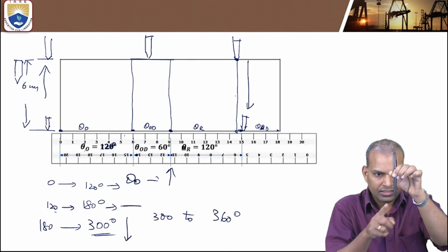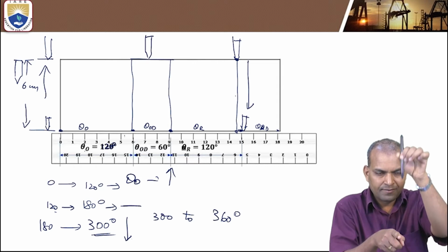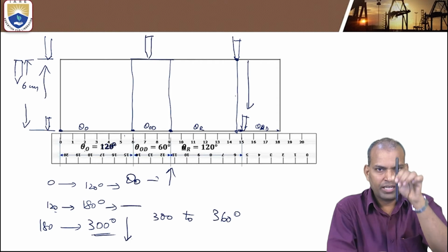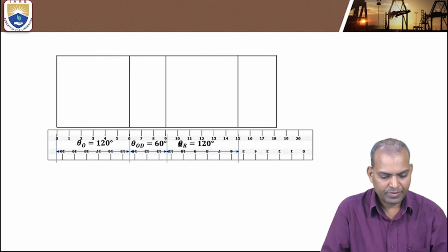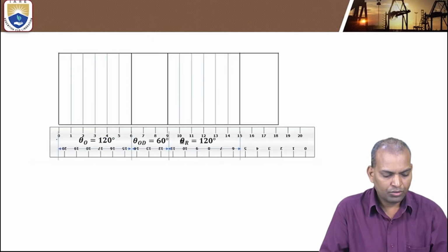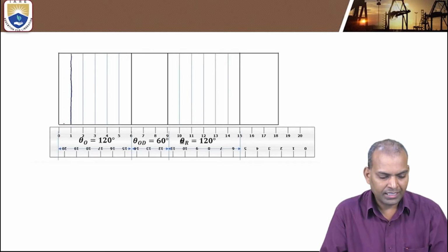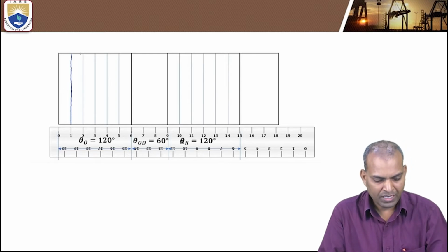When the cam is rotating, the follower remains like that. The cam rotates, it goes on. So this is the displacement. Now for 120 degrees, you have to draw vertical lines. To draw the cam profile, we are drawing a displacement diagram, that is a simple harmonic motion diagram.